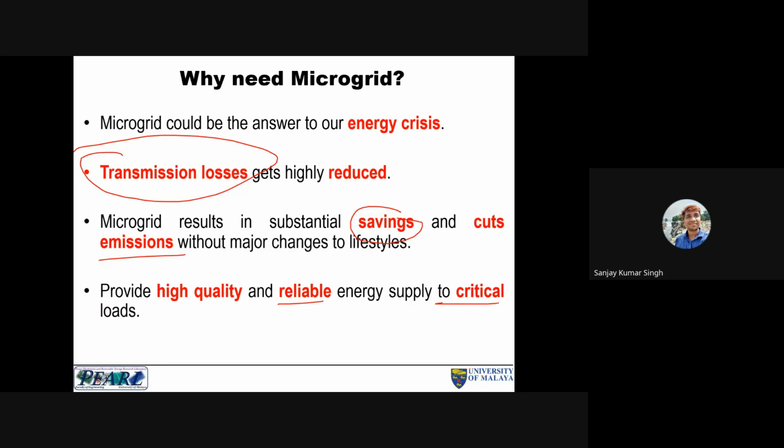Yeah. So we need to keep it charged. So for that, again, we need some source of power, which will be the diesel generator. But it has some time to start up. So first switch on the critical load on battery, then turn on the diesel generator, keep the battery charged, and that is how we can maintain the reliability. Very good. Yeah, that's good.